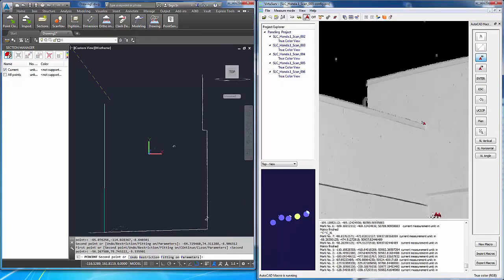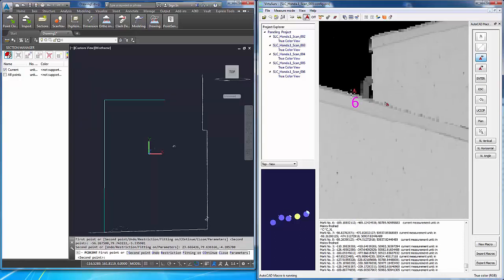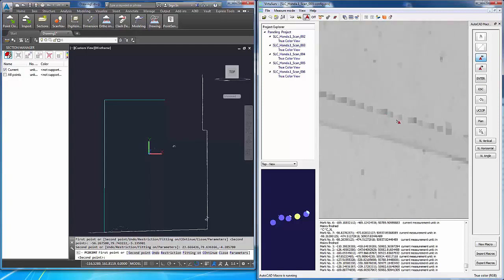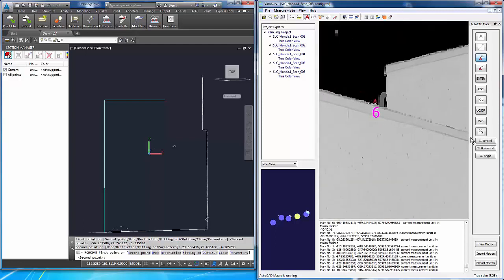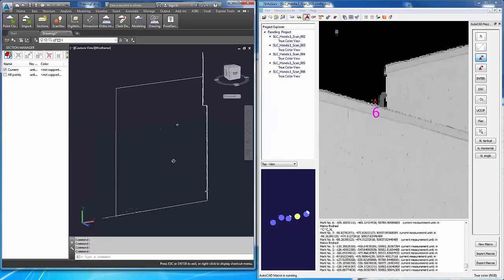On the top side here, I just pick 2 points. It's okay to pick them against the sky, and that way I don't select a point behind, like if I were to try and select this edge here. Then, since I've gotten back to where I started, I just use the close button down here in the command prompt, and we see that we have an elevation view there.